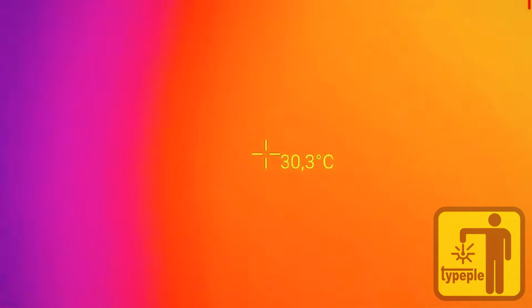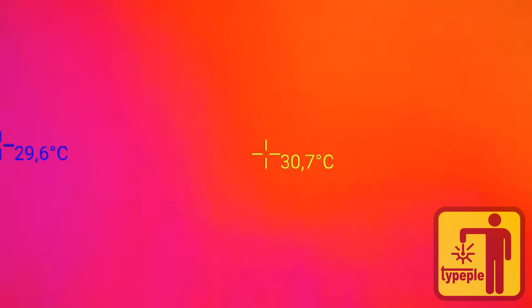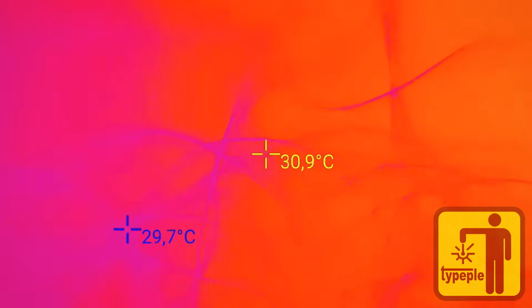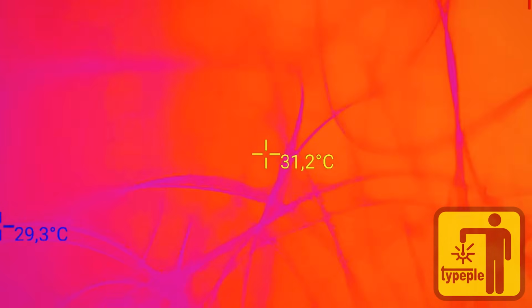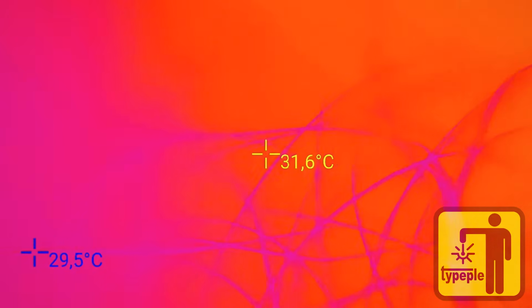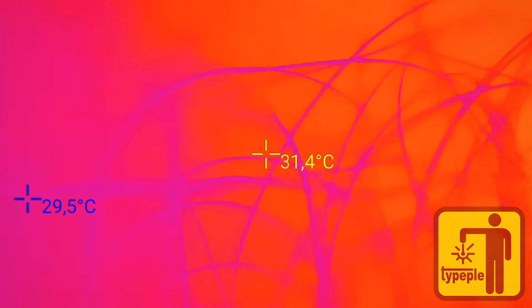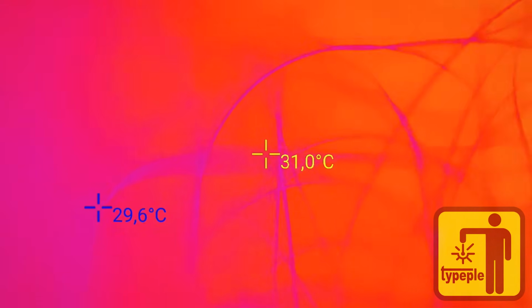What does a zinc selenide lens give us? Let me show you. Basically what electronics technicians mostly use it for. By installing a zinc selenide lens on our thermal imager, we can get an increase of almost 10 times, greater or higher compared to the same standard classic lens. Yes, and that's not the limit. You can do more, increase the focal length, and, well, get a much better result. But even so, we can already see that a detailed view of some small elements under the thermal imager will be much better and clearer.